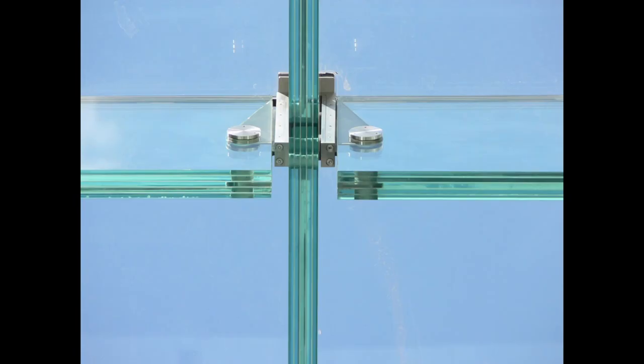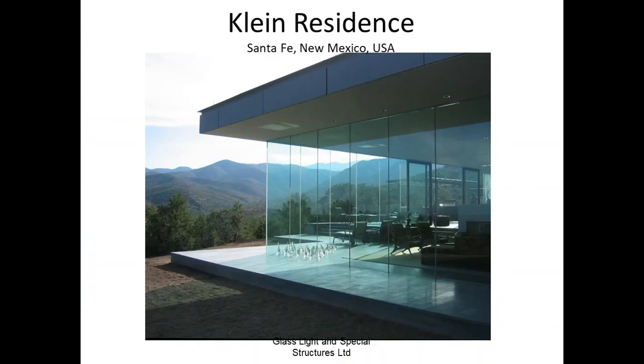So I mentioned earlier that there's a point at which the laminations in structural glass make it possible to take enormous loads. And this building, which I think was completed in 2015, not that long ago, the glass that you're looking at here is a load-bearing wall. There's no tricks going on anymore. There are no other columns, so the roof is being carried by the glass, as you can probably see inside.